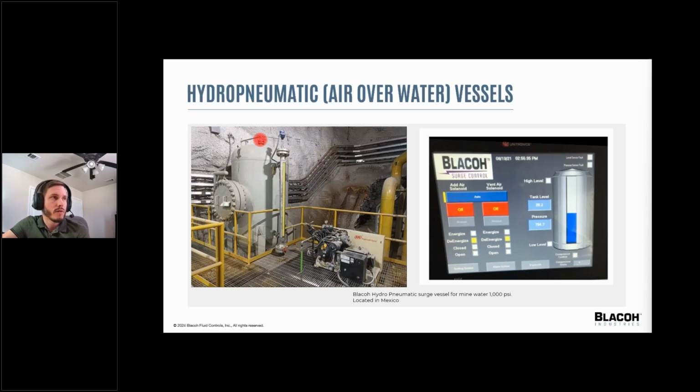The programmable controller receives a pressure signal from the pressure transmitter and a level signal from the guided wave transmitter, and it decides when to actuate each solenoid valve with a time delay. For hydropneumatic vessels, the air gets added while the vessel is online, so the associated precharge pressure must be determined from the liquid level and operating pressure rather than directly measured. When the operating pressure range is small enough, the precharge pressure range can reasonably be determined from just liquid level.